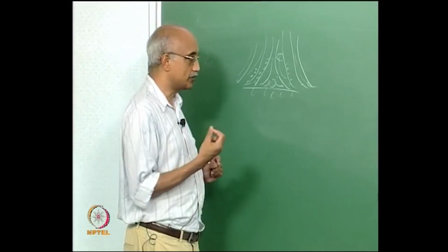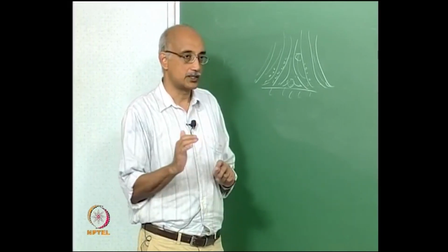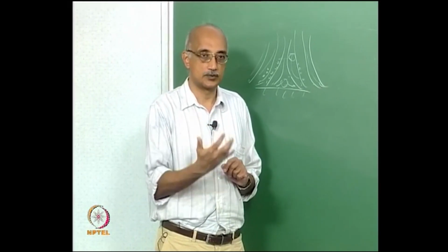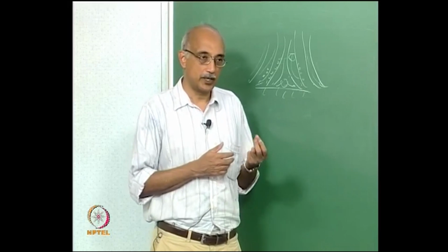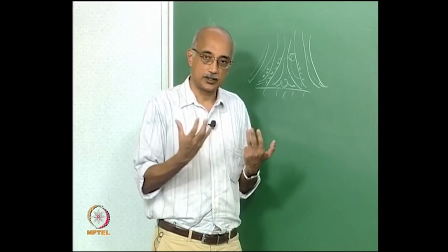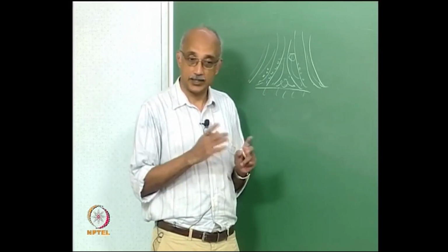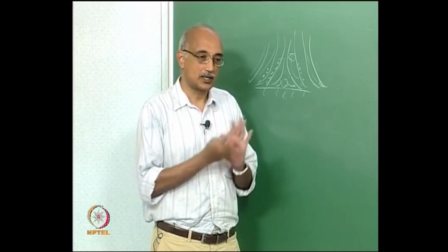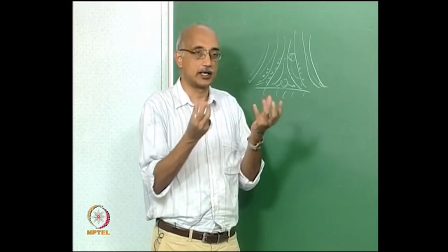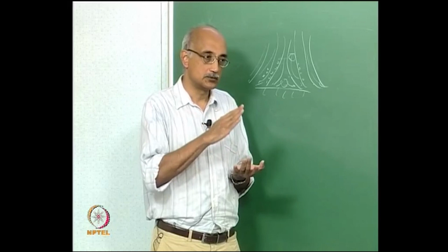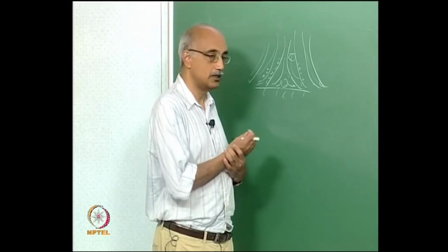So, the measure of inertia is really the tendency of the particle to behave in a fashion that is completely different from the carrier fluid in terms of its transport characteristics. And inertial effects will obviously depend on the size of the particle. As the particle gets larger, it will have a greater tendency to separate itself from fluid streamlines. When that happens, you have to essentially start considering the particle as a separate phase. You really cannot assume that it is behaving like a heavy molecule. So, there is a limit of size once it crosses which the effects are definitely inertially dominated.